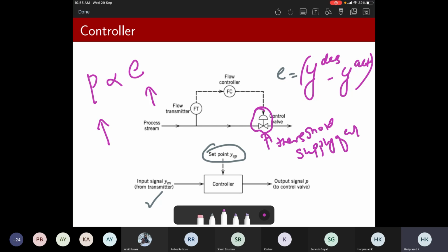It's called a sticky phenomenon. It's like what you have heard about Bingham plastic fluids and things like that. You need to apply sufficient stress to initiate the flow. The same way you need a threshold air supply so that the valve would start opening. Of course, we will talk about that later. There are various types of control valve, which is also called quick opening.